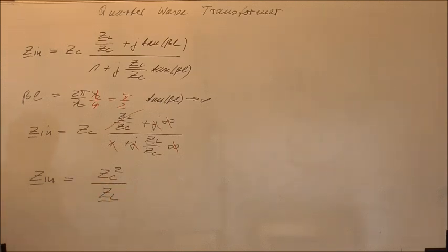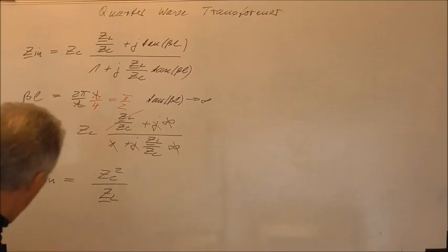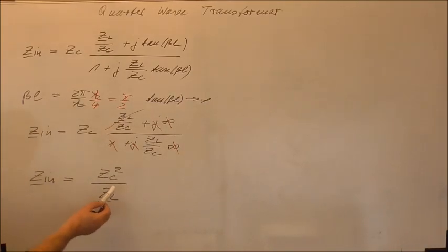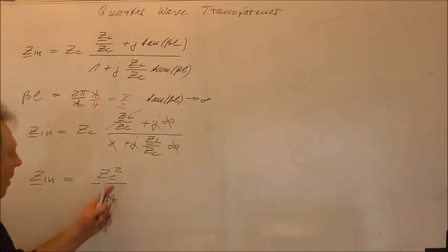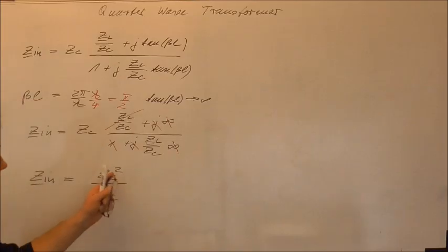So normally we assume the load impedance to show a complex value, but we can also assume that, for example, if the load impedance is real, then also the input impedance will show a real value, because in RF engineering the characteristic impedance is always a real value.